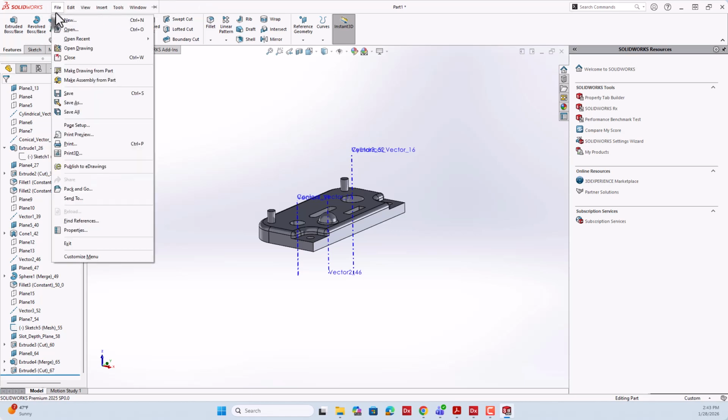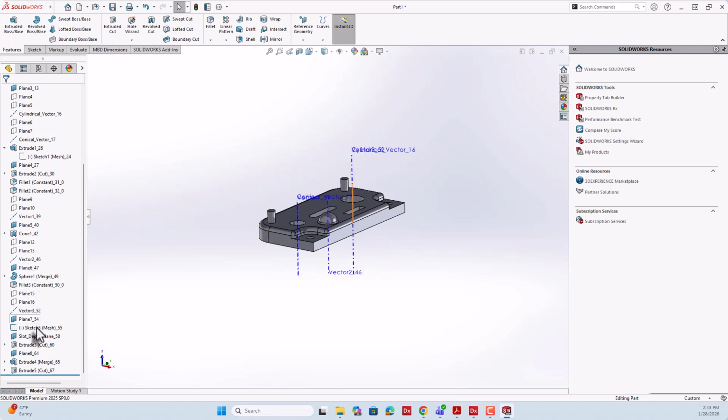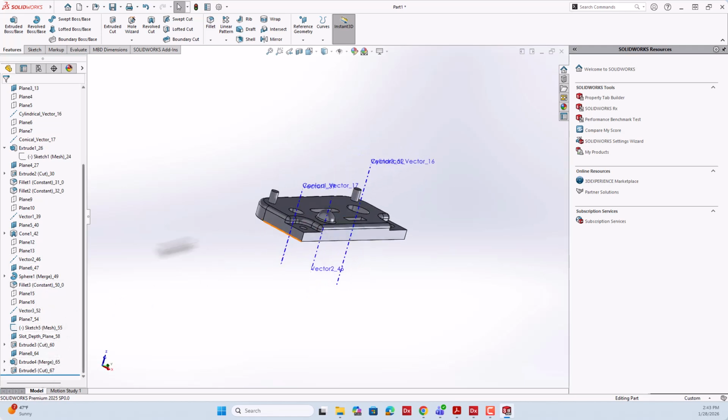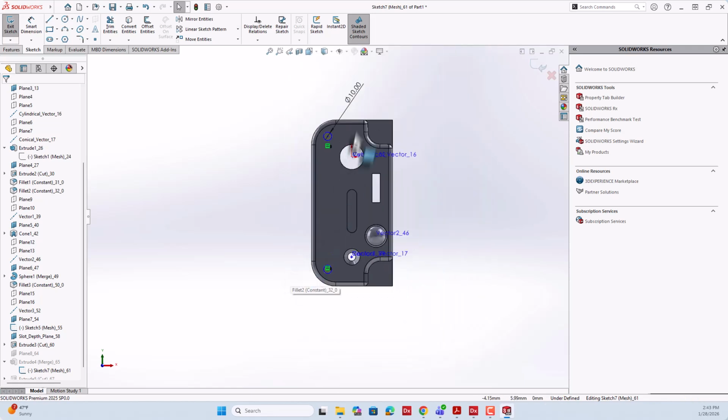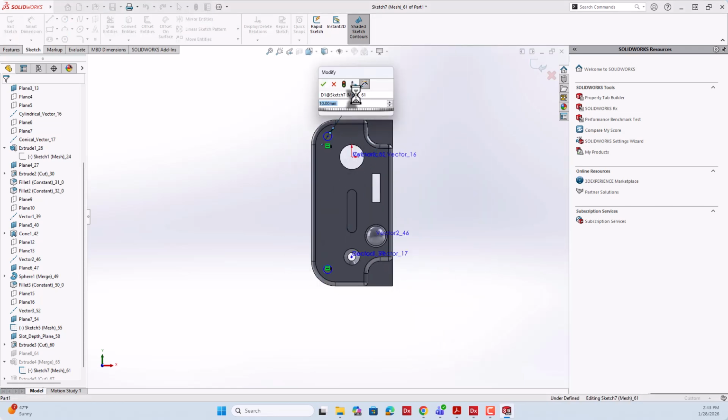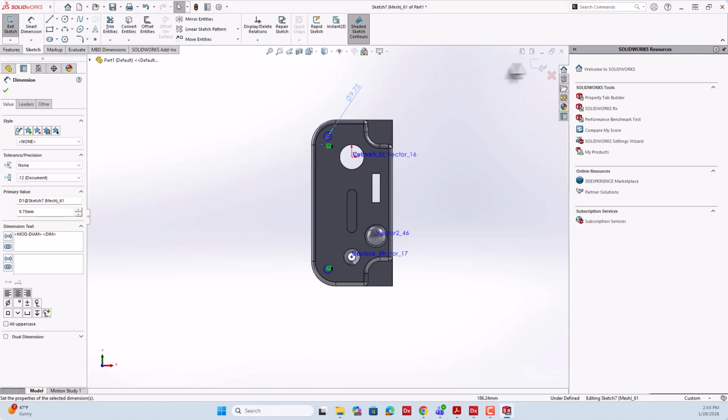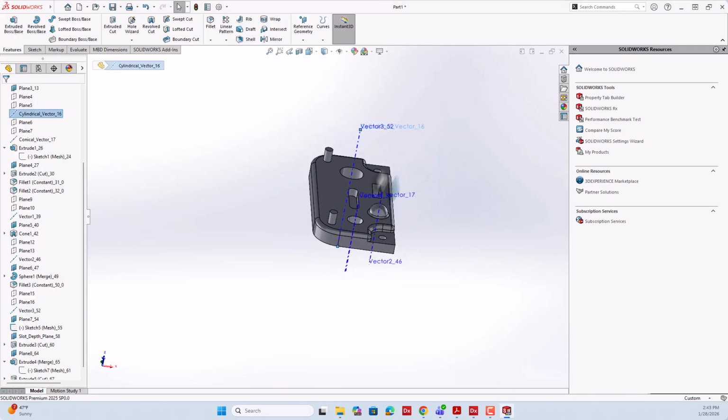This file at this stage is an independent SolidWorks file that you can export and work on. So you can save this as a SolidWorks part file, and you have the complete modeling history along with all the names of whatever items that we put in. Everything has come over here completely. This process is called live transfer, and ensure that you get the complete modeling history, so that if you need to change any particular dimension, you can change it in the SolidWorks itself. So I can come here, and if I want to change this from 10 into say 9.75, I can enforce that change, and the model would update in SolidWorks appropriately.